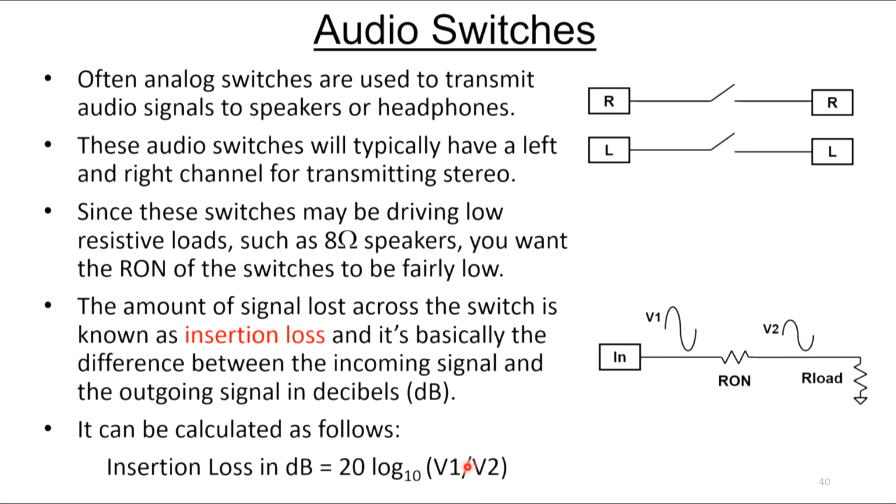So you take the ratio of the signals and take 20 times the log of that. And that's insertion loss. It's just a measure of how much power or energy you're losing in the switch.